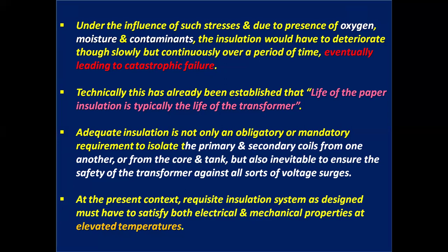Adequate insulation is not only a mandatory requirement to isolate the primary and secondary coils from one another or from the core and tank, but also inevitable to ensure the safety of the transformer against all sorts of voltage surges. In the present context, the requisite insulation system as designed must satisfy both electrical and mechanical properties at elevated temperatures.